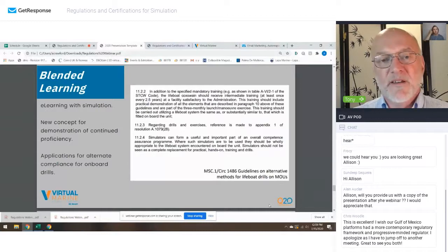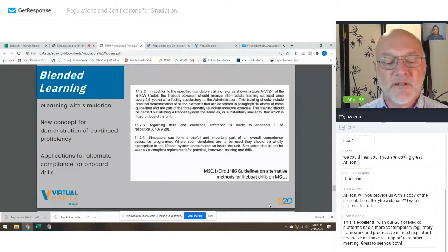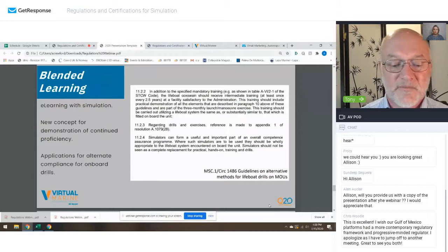But then when you start getting into specific applications, I'm picking lifeboats again because this is probably where the most feverish activity is going on right now. In the offshore industry, there have been so many accidents. In fact, it's not just offshore, it's around the whole industry. So many accidents during lifeboat drills that the MODU code was changed. And the MODU code now allows an alternate compliance mechanism for doing onboard drills. And this is the alternate compliance mechanism. It's MSC.1/Circ.1486.